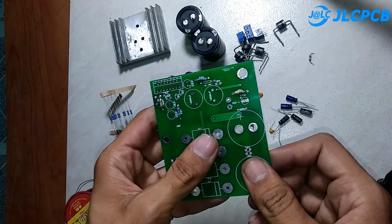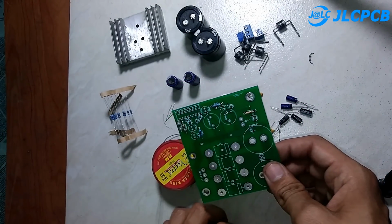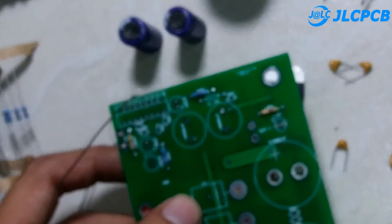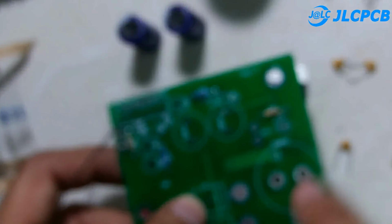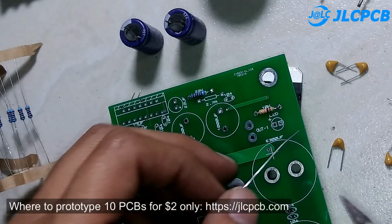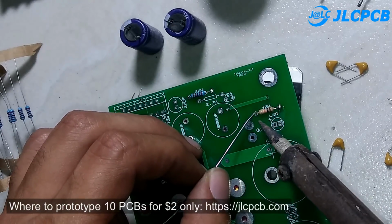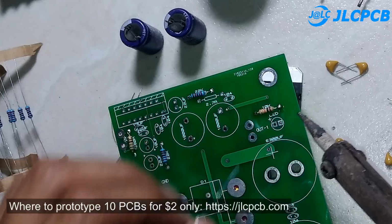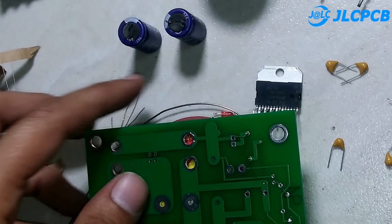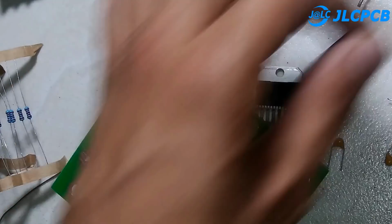As it is a 2-layer board, you can solder from the front side also. I'll show you how. Here you can see this 10 kilo ohm resistor which is not soldered yet, and I will solder this resistor from the upper side of the board, which is the beauty of the 2-layer board provided by JLCPCB.com. So here we go, it's soldered now. This will save you a lot of time while soldering the board.